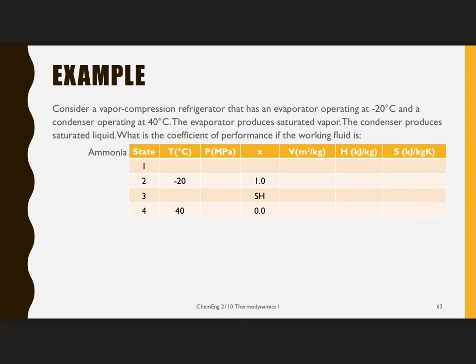And finally, what about ammonia? What I found was the pressures range from 190.2 kilopascals to 1,555 kilopascals. The high temperature is 135, much higher. I didn't find the quality. I didn't look that up, sorry. Enthalpy is 371.43, 1418, 1737, 371.43, all much larger values of the enthalpy. And our coefficient of performance is 3.28.